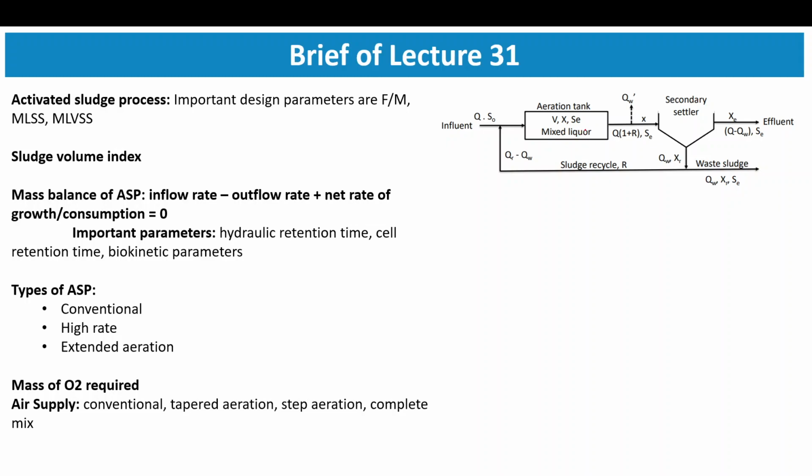They grow by the digestion of the organic compounds or any other compounds that can be oxidized. The activated sludge process occurs under a constant supply of oxygen. Now, a lot of sludge will be produced during this, because of the growth of microbes.